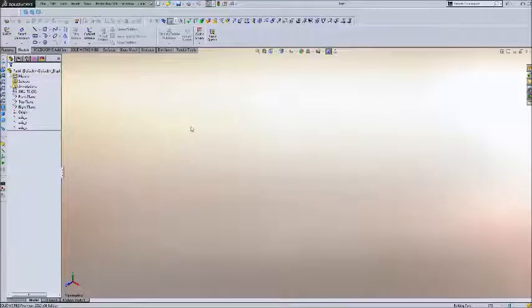Alright, let's get started. Before we start doing the actual CAD, I'm going to go over a little bit of science around gears just so you can get the terminology down. There's a few ways you can define a gear. Gears are defined by tooth count, which is, as the name suggests, how many teeth they have. They're defined by diametrical pitch and pitch diameter. Pitch diameter is essentially the point at which two gears mesh. Diametrical pitch talks more about the spacing between each tooth.